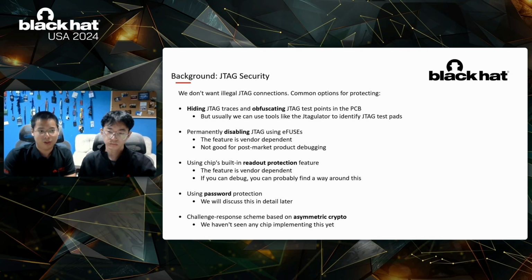Some vendors would choose to permanently disable the JTAG. However, some chips do not offer this functionality. Also, disabling JTAG altogether is probably not good for diagnostics. Once the product is out in the field, we cannot diagnose the products for further issues.